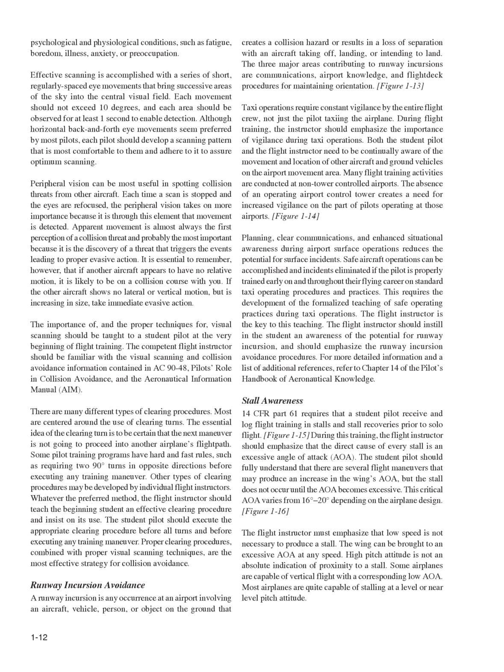Figure 115. During this training, the flight instructor should emphasize that the direct cause of every stall is an excessive angle of attack, AOA. The student pilot should fully understand that there are several flight maneuvers that may produce an increase in the wing's AOA, but the stall does not occur until the AOA becomes excessive. This critical AOA varies from 16 degrees to 20 degrees depending on the airplane design.